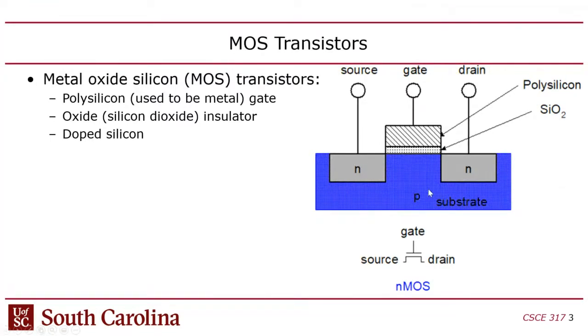And then semiconductor would be the body of the transistor, or the substrate, which is referred to as a semiconductor because it is not only pure crystal silicon, but it also is doped. If you have silicon that's not doped, I don't believe that's referred to as a semiconductor. Maybe it would be, but no one uses pure silicon for anything, as far as I know. It only becomes useful when you dope it, because doping allows you to change the conduction characteristics.